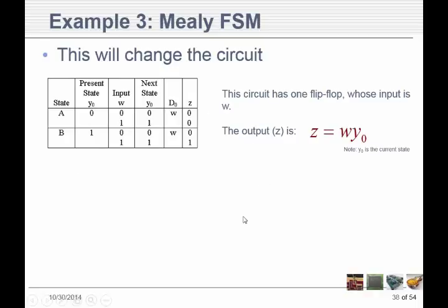You could have a sequence detector that has two variables, right? So that if, let's say, the inputs were R and S, and if R went high twice in a row and S was low twice in a row, then it should go high. So it'd have to be both. And that would get a little complicated, but you could do it.